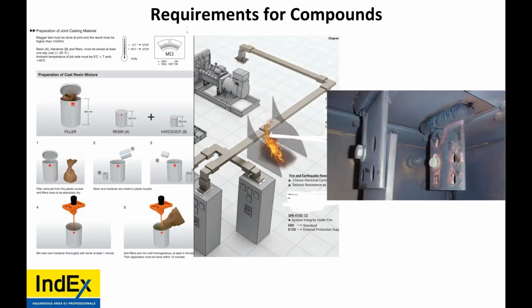So what are we looking at? Well, the reason the manufacturer has these Ex m bus ducts is that, instead of using cables, you can use something that is earthquake proof, fire proof, and can transition zones. It can go between a non-hazardous area, a zone 2 and a zone 1 all the way.